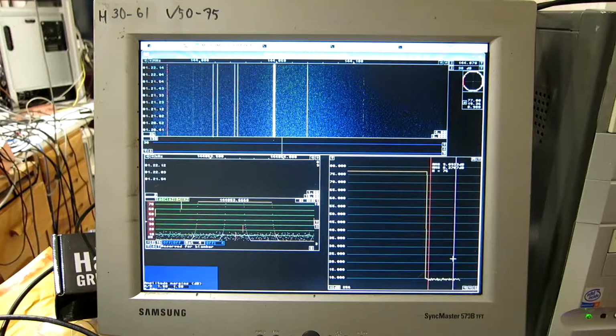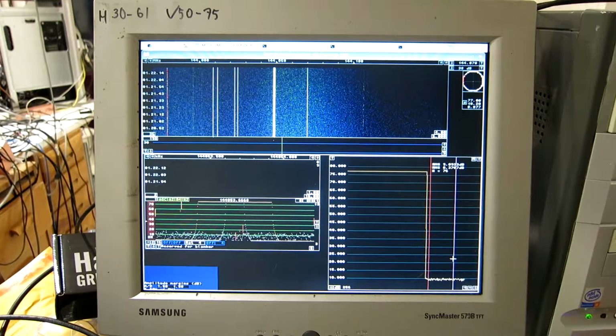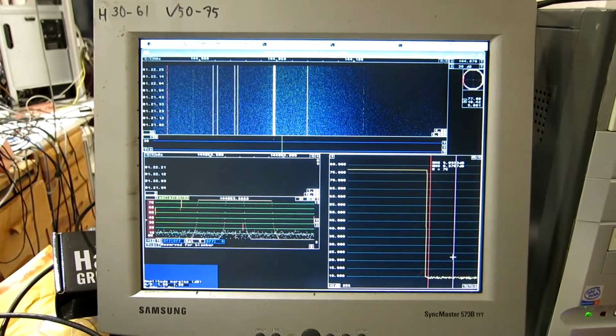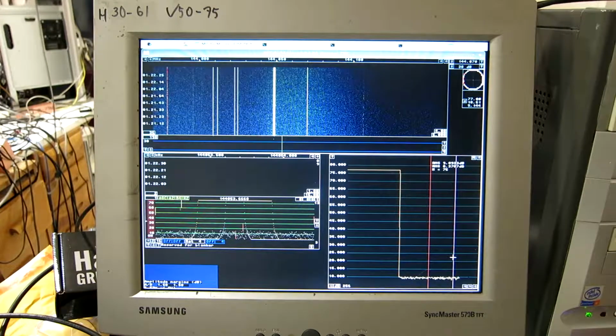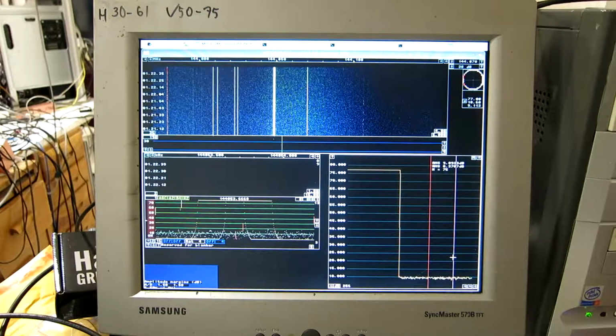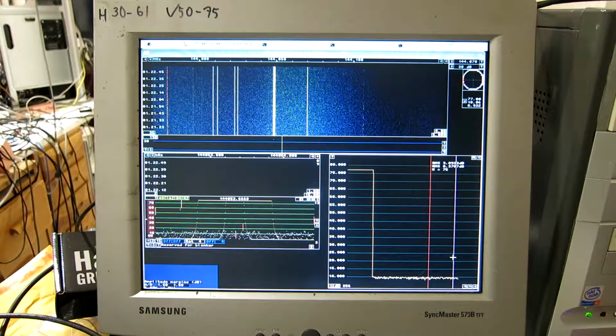It's 9.1. And that is a dynamic range of 67.9. Or let's make it 68. I had 74 at the higher sampling rate, and I have lost 6 decibels by reducing the sampling speed from 900 kHz to 300 kHz.